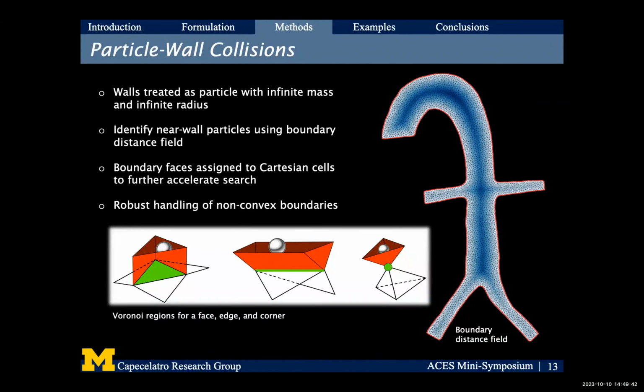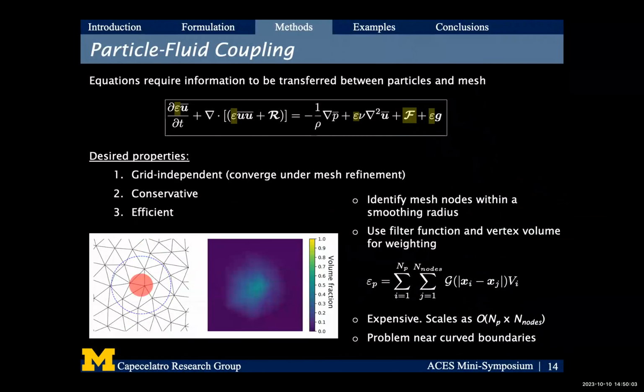What we do is make use of a Voronoi tessellation and then search each particle to identify what kind of collision this could be. Is it with a convex edge or a concave one, or is it a point? We have to go through this sort of identification before the collisions happen. But that's taken care of. The final part I want to mention here is this two-way coupling.